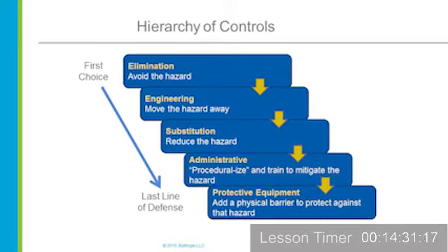Other measures they can take are substitution, but that's not really an option for a pharma company either. They have administrative controls, and those certainly will be used as this covers the creation of standard operating procedures in the workplace, putting up labels and signs, and even conducting some safety training for their employees. And then lastly is the use of PPE, or personal protective equipment, which can work well. Industry uses these quite a lot, but if that PPE fails or the worker doesn't use it properly, really there's going to be a high likelihood of an exposure.